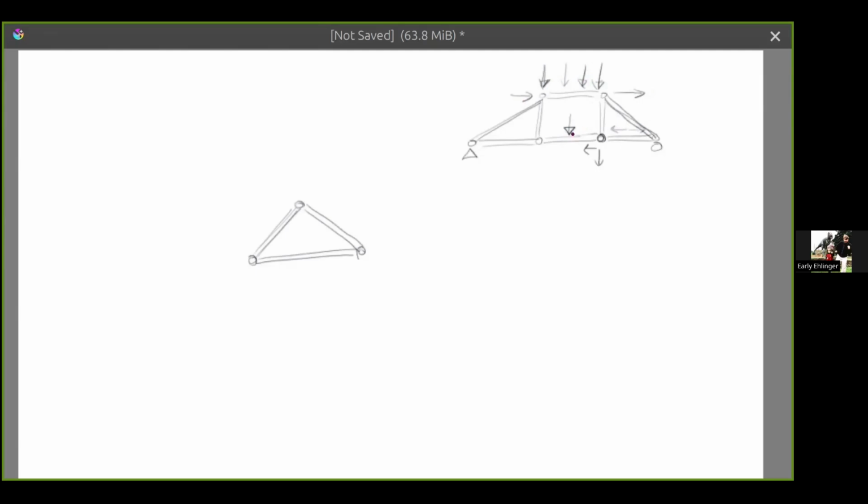And we can have twisting applied, but the twisting has to be oriented about effectively the z-axis, so that everything that happens in the structure stays in the same plane as the structure. That means this structure is two-dimensional, just like a beam.